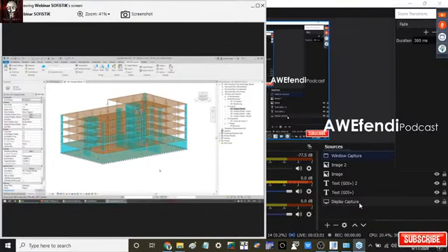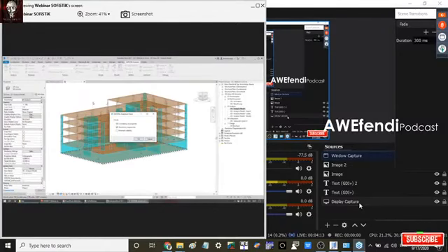So there might be errors or inconsistencies within this model, and it is often a relatively tedious task to clean up the model such that it can do an analysis. And in order to support that process, we are providing an analytical check, to check the model prior to analysis.